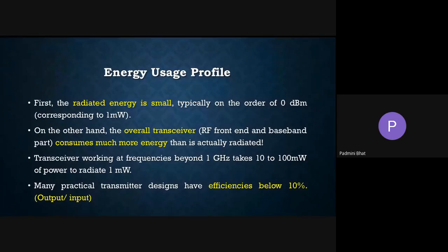Now when I'm talking about wireless sensor network, I am going for a very compact entity. In that, if the antenna height itself is a hurdle, if you tell me that I want to have a 15 centimeter antenna, or around 100 centimeter antenna, then how can we design? Only the antenna will be very large compared to all my other devices. So that is not possible. If I reduce the antenna, then again my wavelength has to be reduced. So how does the trade-off have to be done?